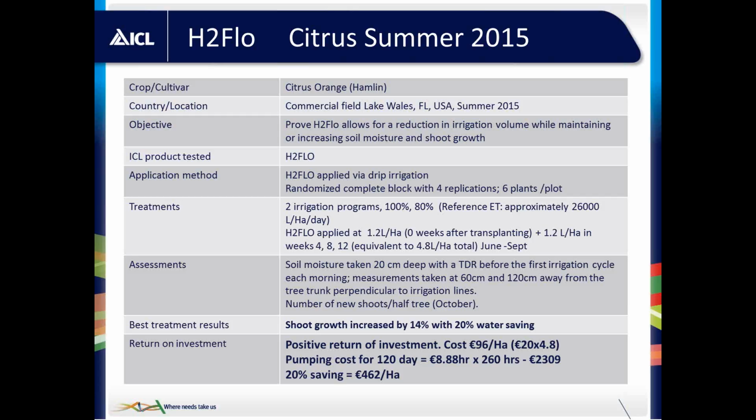And in terms of return on investment, we didn't look at yield in this case because the trial is still running. But again, we had a similar cost, so 96 euros per hectare. But the pumping cost for running this particular crop for the 120 days, it worked out at 8.88 euros per hour, and it needed to be run for 260 hours. So you had a total cost there of 2,309 euros. So a 20% saving on this cost is equivalent to 462 euros a hectare.